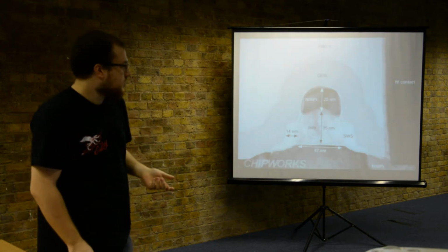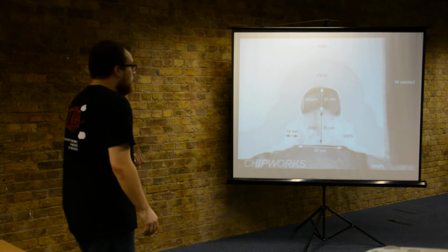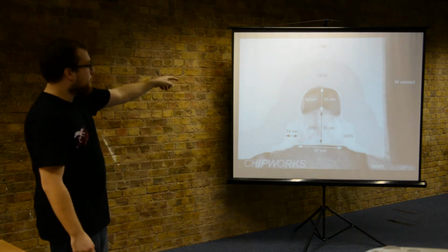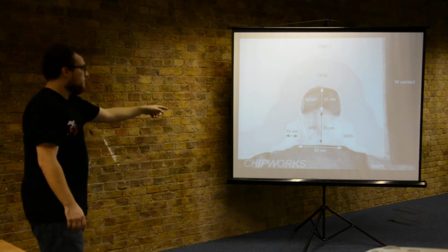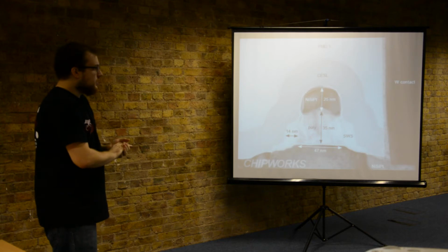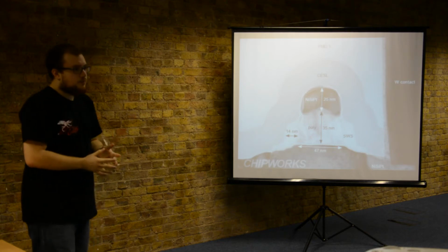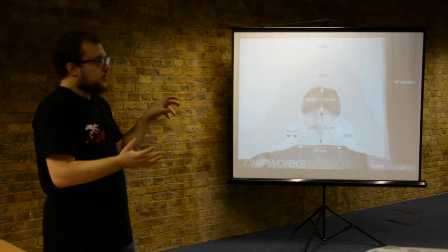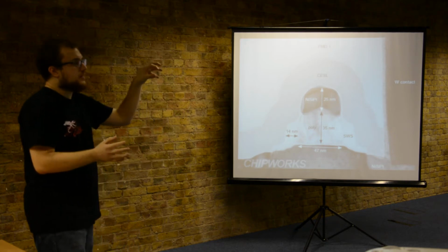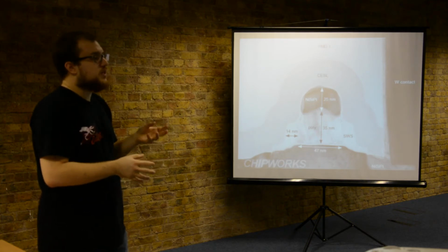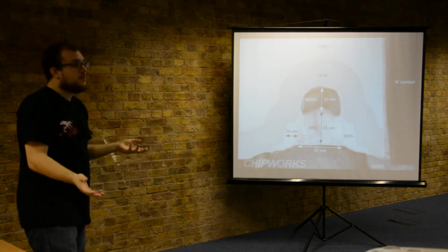And this is a cross-section of a transistor. And the future sizes we're looking at are 25 nanometers, 35 nanometers, and 47 nanometers. So as you can imagine, these devices are far from perfect. One transistor that you have on one side of the device is not going to be equal, or its characteristics are not going to be exactly the same as the one on the other side.